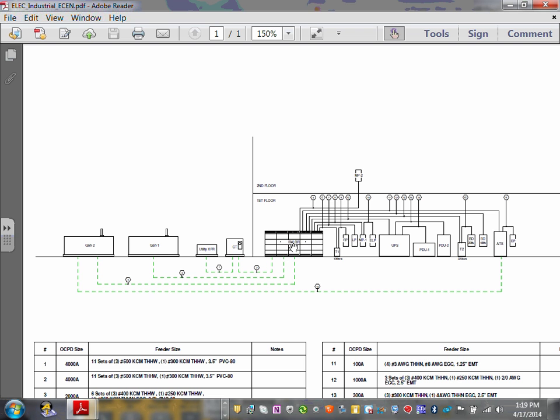So to summarize, guys, we'll have a service panel, service equipment here, and from the service equipment, you can start taking chunks of loads inside your building for the lighting panel, receptacle panel, mechanical panel or panels, UPS, as well as owner equipment. So that's what we typically handle as engineers and electricians: you handle a panel.